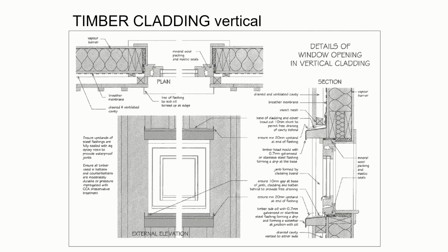And these details have been developed up over many years of practice, but they all rely on air to be able to dry out the timber, and battens to be able to create spaces in these. So if you look at this detail, which I think is from a book called Timber Cladding in Scotland, we've got the same kind of details round about the head. We've got battens that are cut backwards to a fall. So they all do the same sort of thing.